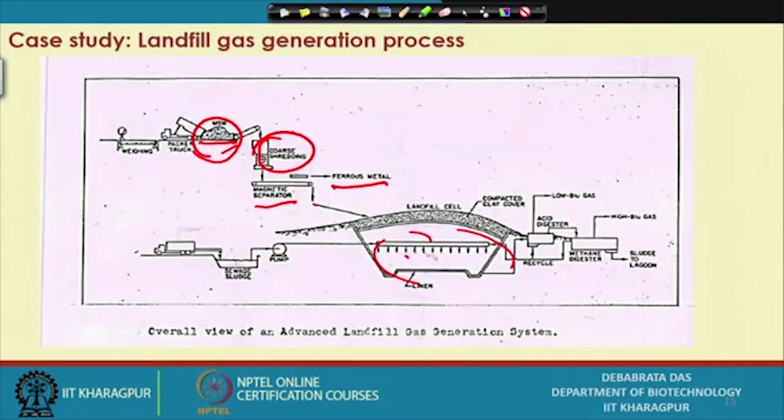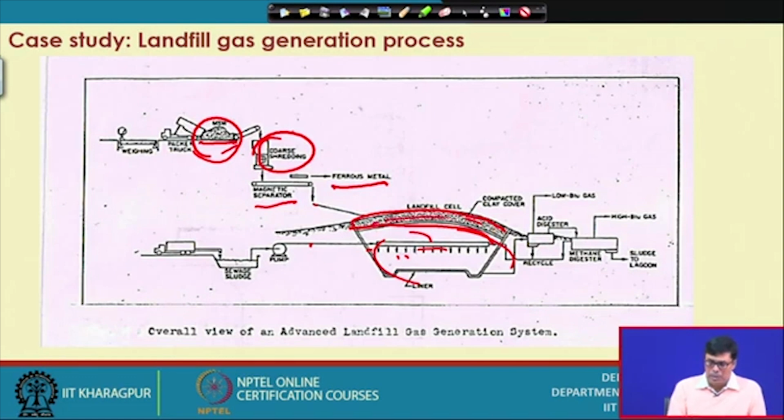Otherwise, gas will be generated from the solid material and pollute the atmosphere, which is undesirable, so they follow this. And when it is totally filled up, it is covered with about an 18-inch thick clay layer, just to ensure no gas will go out from the system. Then we make some kind of well here,